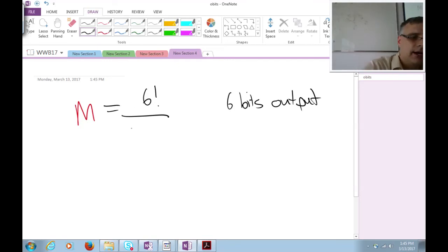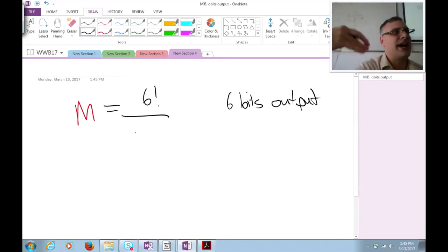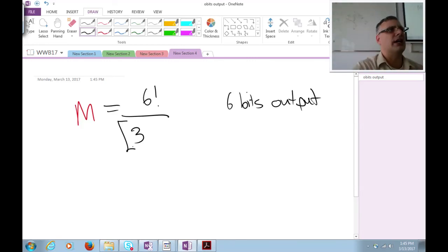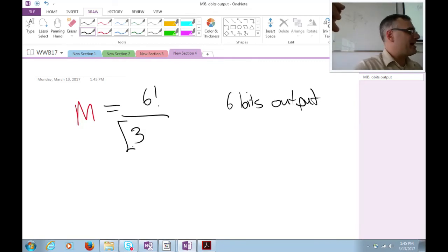How many balanced code words should there be? Well, it should be 6 divided by 2 factorial, so that would be 3. Notice that you can't plug odd code bits into that formula, otherwise you'd have like 5/2 factorial. Why can't you put odd number of bits into that formula? Because you're going to have balanced codes. That's right, you're always going to have one odd man out, poor odd bit out. There's no way to balance an odd number of codes, so it's convenient that the formulas don't work either, right?